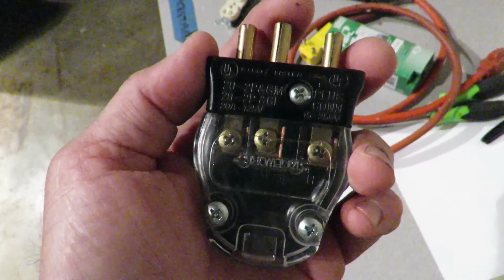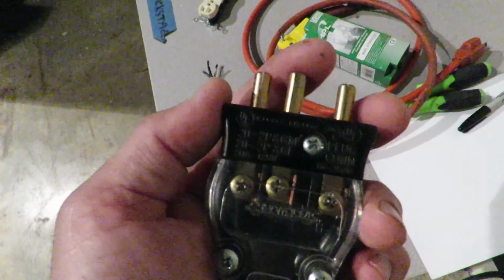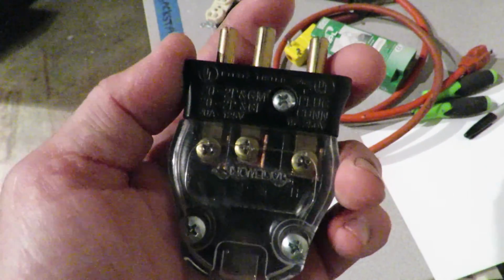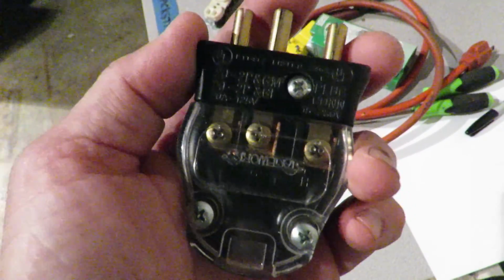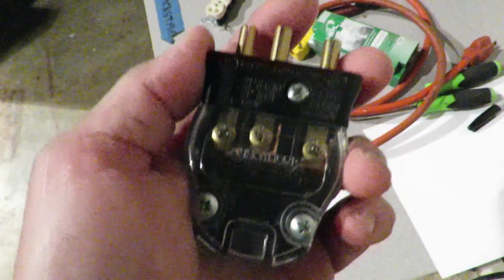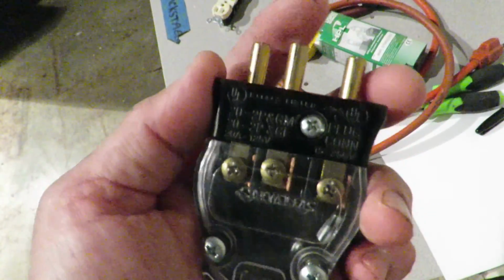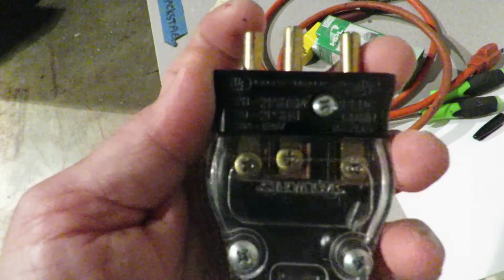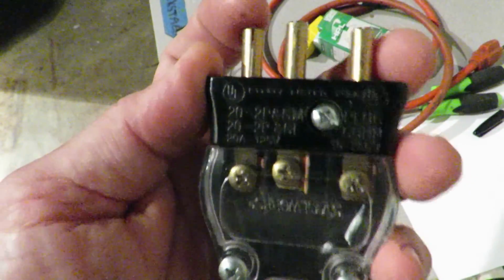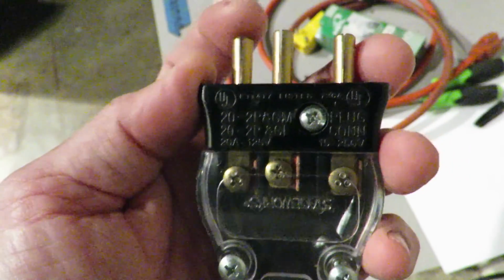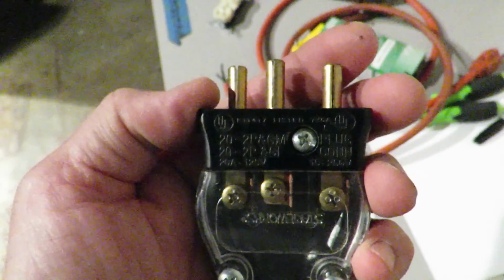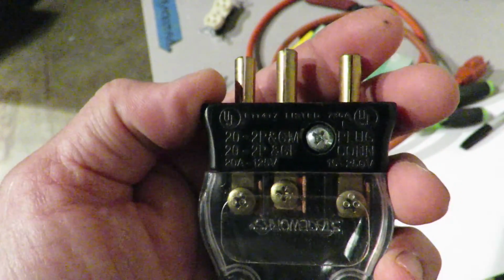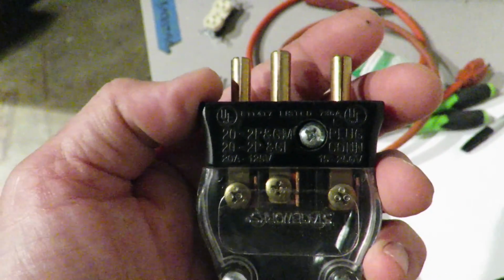The green wire is what you hook up first. You always hook the green wire up first so that whatever it is that you are working on will be grounded. And then you would hook up the white next, and the white goes on the pin that is closest to the green. And the last thing you hook up is the hot wire. And if you were taking something loose, you would do it exactly in the opposite direction.